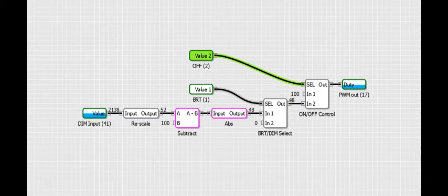All right, so let's take a look at what happens here graphically on the PoBlocks code. We've got monitor mode on. We're running the code in real time. Now I'm going to go over to the workbench and I'm going to vary the pot, and you're going to see these values go up and down. All right, so now you see that I'm turning the pot all the way one direction and all the way the other direction, and you can see the pulse width modulation values change as well as the analog input.